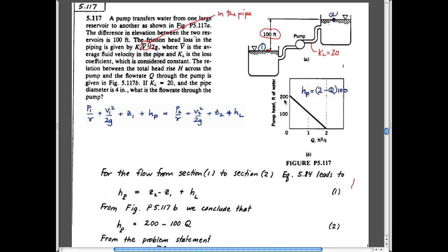So this is the pump characteristic curve, I guess. It says that if you're only flowing a very little bit of fluid, then it can actually pump against a big head, and it can provide a lot of power because it's not working flat out. If it's moving a big volume of fluid, then it really can't push it very high, which is kind of what you would think. Actually, if you think about it, this looks just like our force versus velocity curve that we used to talk about the amount of work in a system, right?